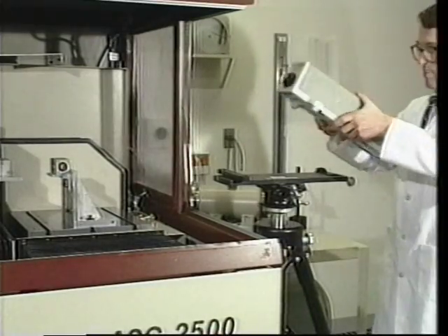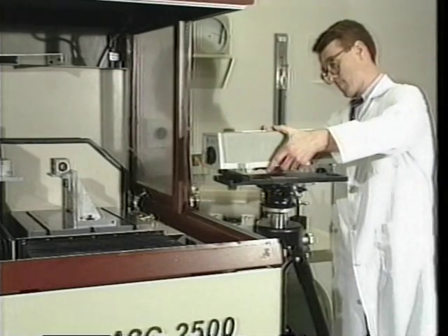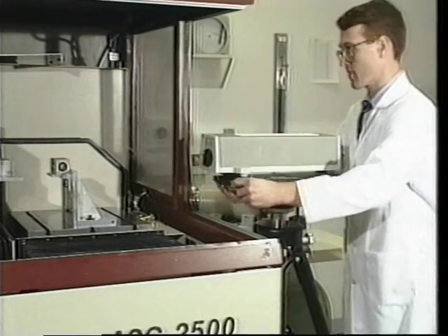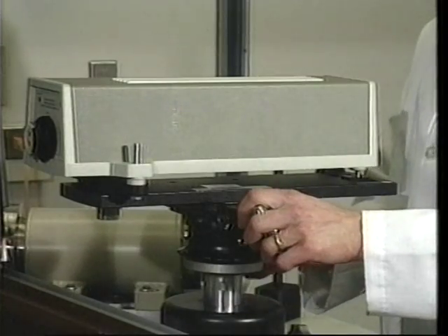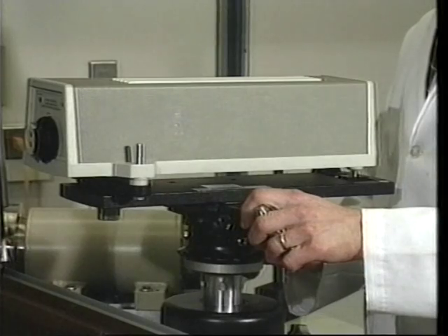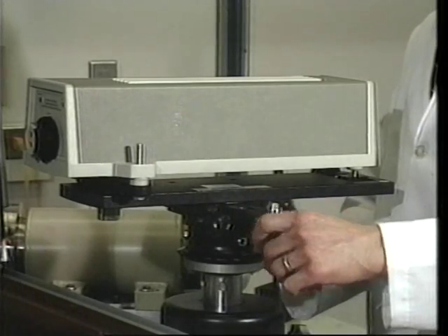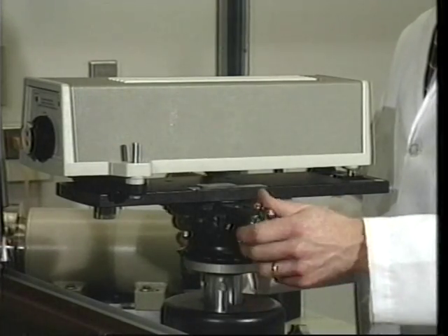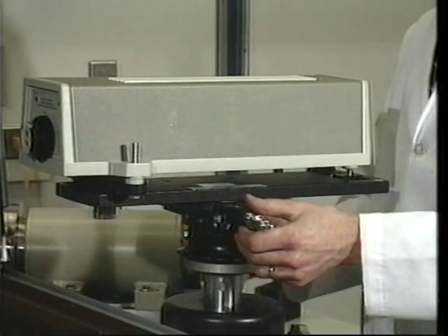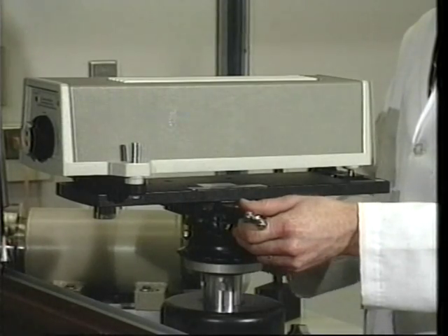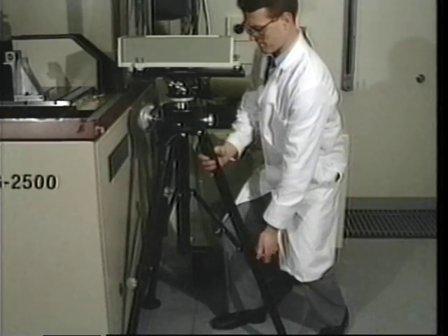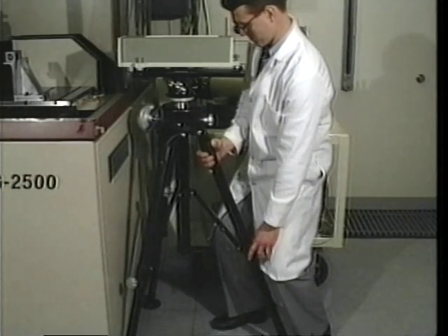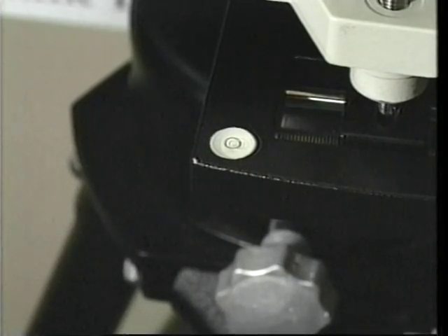After both the reflector and the interferometer have been aligned with the machine axis, the laser head is mounted to the tripod. Using the tripod adjustments, the assembly is nominally aligned with the reflector and interferometer. Note that the laser head and tripod are positioned as close as possible to the DTM in order to minimize the effects of air path fluctuations. When the tripod position has been established, the laser head is leveled by adjusting the lengths of the tripod legs until the bubble level is centered.